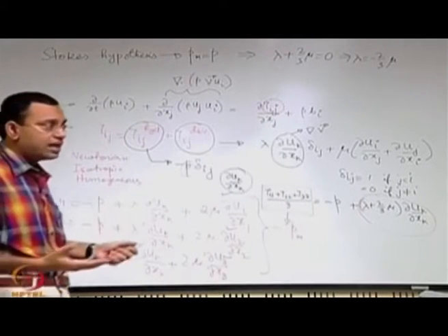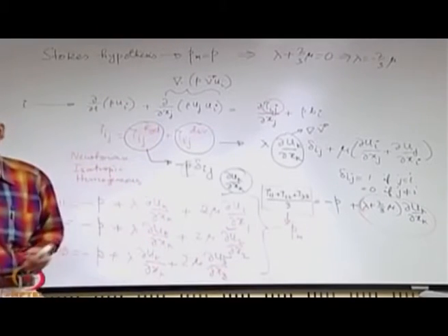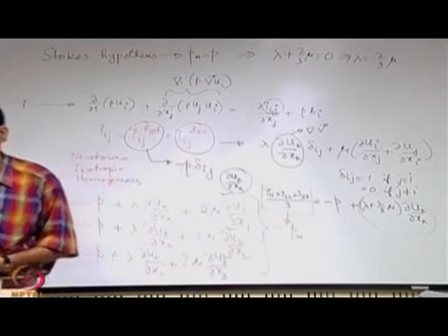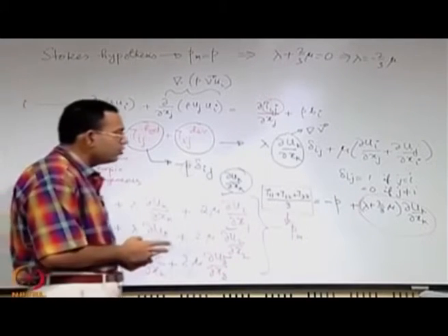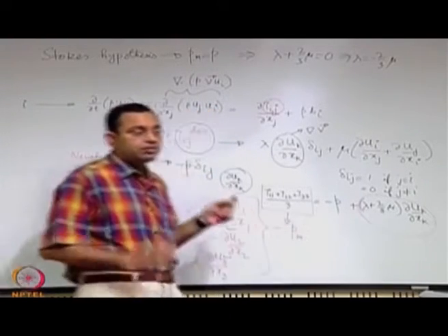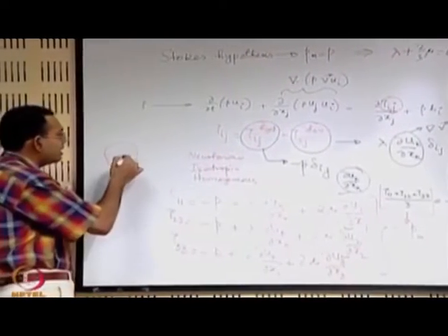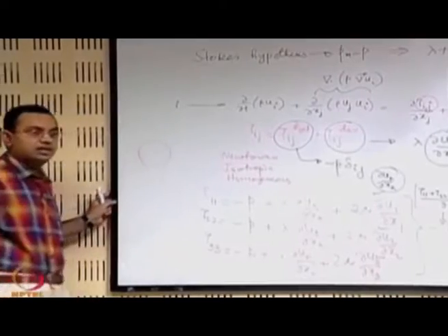But all substances, even if we think of gases or compressible substances, are not dilute monoatomic gases, and therefore for all substances you will not have mechanical pressure equal to thermodynamic pressure. But we have to understand what the expectation is. The expectation is, let us say that you have a bubble, inside the bubble you have some gas, and let us say that the bubble is changing its state.